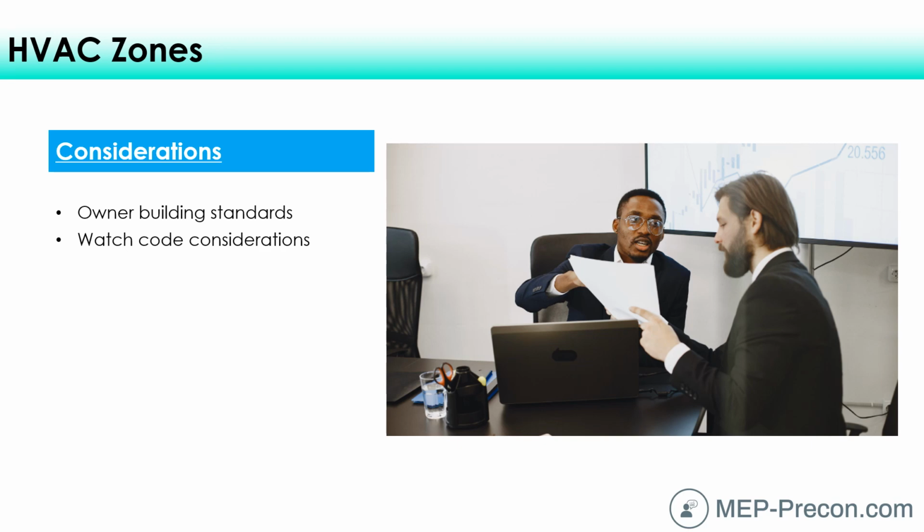So in conference rooms, if there's nobody in a conference room, well, let's not provide a bunch of fresh air in there to heat and cool all that fresh air. If it's cold outside or if it's hot outside, let's close that down. But if it senses there's a lot of people in there, not just an occupancy sensor, a CO2 sensor would do something different than an occupancy sensor.